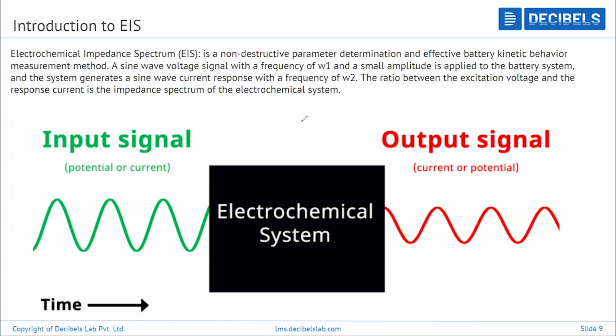So here is something we call the EIS sweep. The word EIS sweep means conducting it like this: applying an AC current at some particular frequency and with small amplitude, with the frequency itself being the variable.